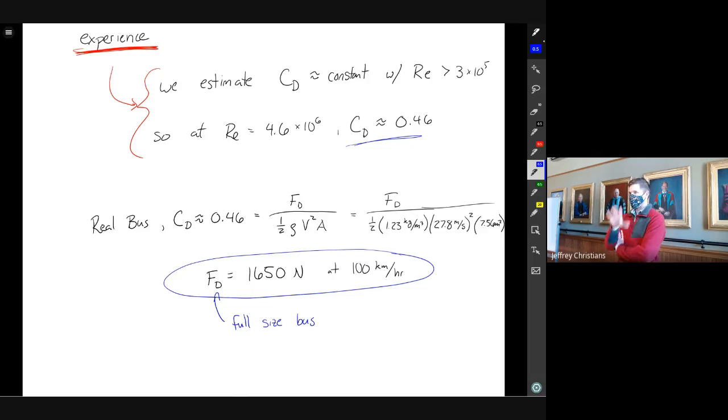Another common example, like objects in cars and buses, is aerodynamics, where we commonly run into this. Another example where you really always run into this is drag force on large ships. You pick and choose, because we can only partially match the conditions. So you have to have a lot of experience with how to design good models of these kinds of objects. We still try to use some of the same guiding principles for how you design those model systems, but in practice, it's not always clean cut.